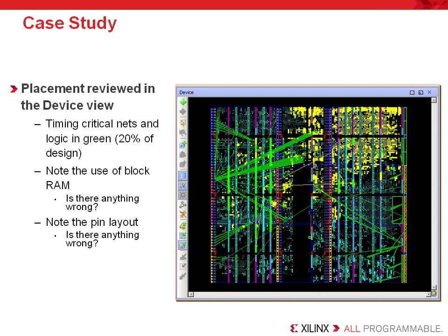In the critical hierarchies, there is high utilization of the block RAM. The non-critical hierarchies contain a lot of LUTs and flip-flop logic that can be placed between the block RAM. The entire hierarchy is approximately 20% of the design.